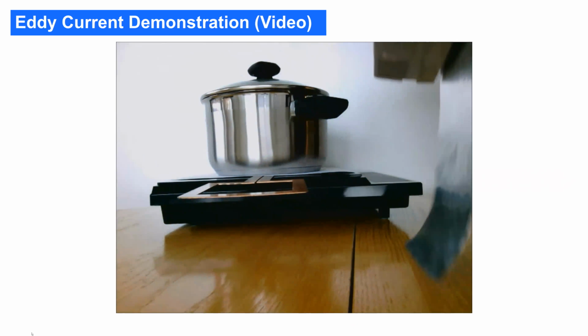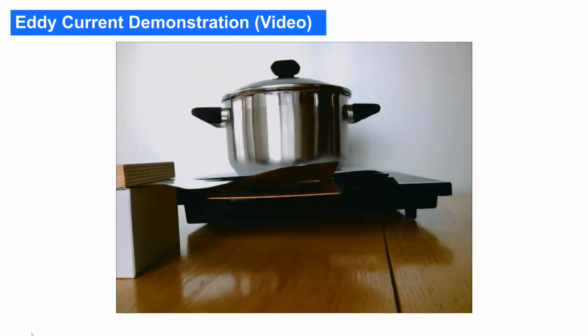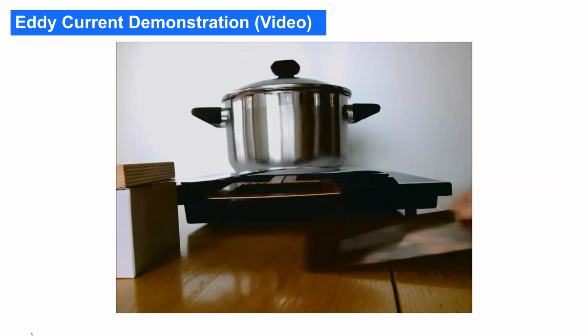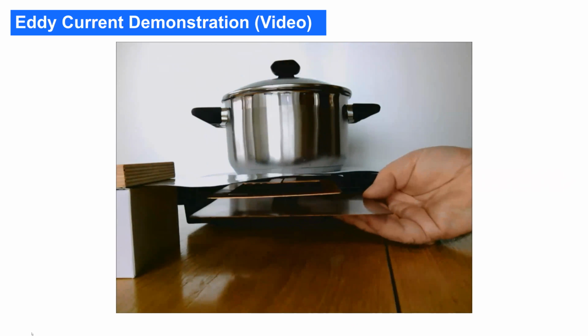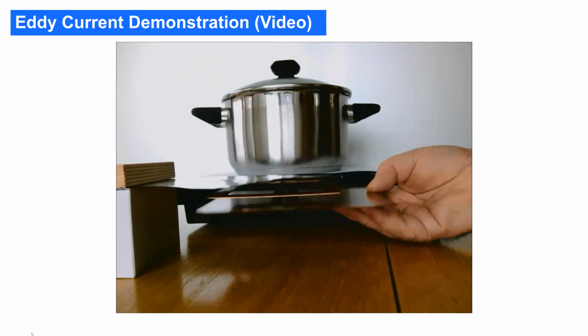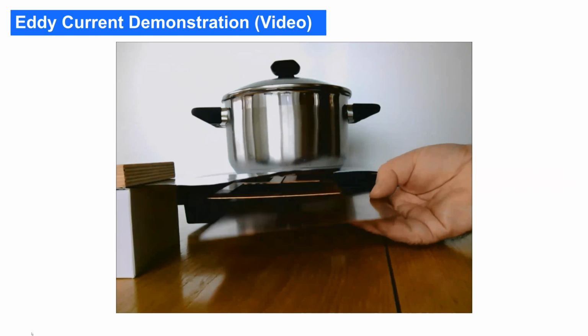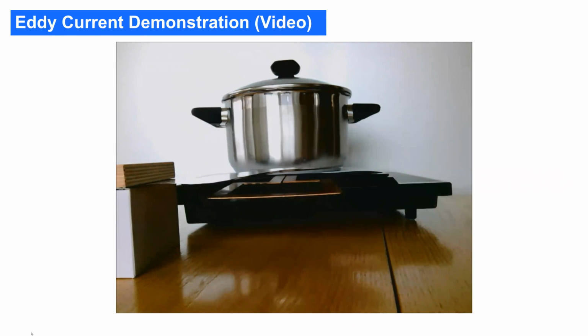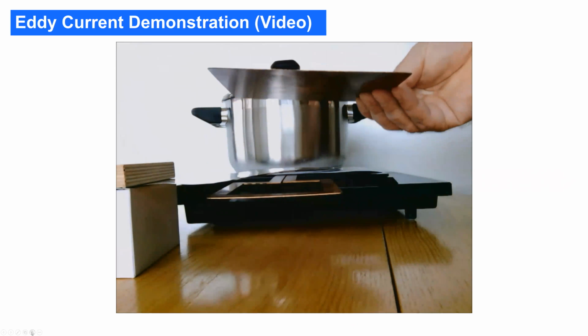Now I place an aluminum foil on top of the loop, and if I switch it on, the aluminum foil will fly because it creates eddy currents. If I put a ground plane, or a current conducting plane, under it, it actually reduces the height of the aluminum foil, which indicates that the eddy currents are lower.